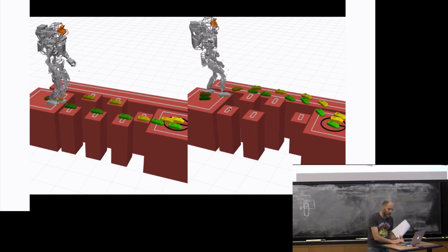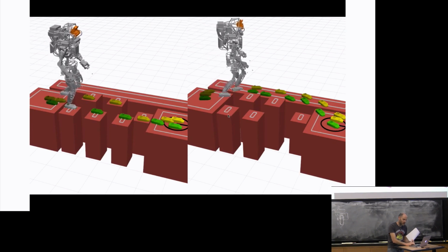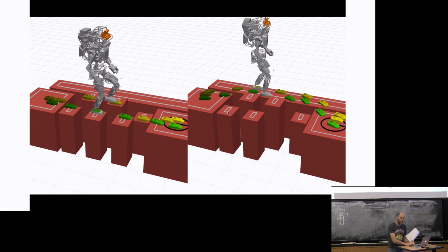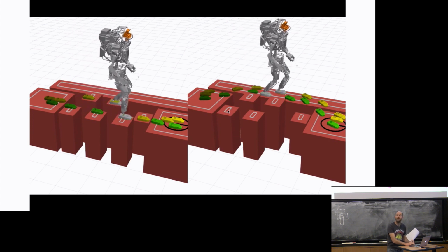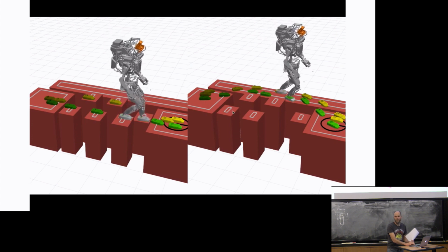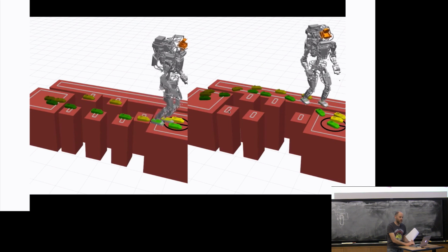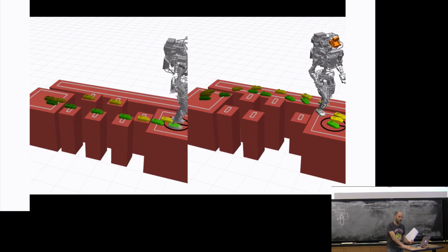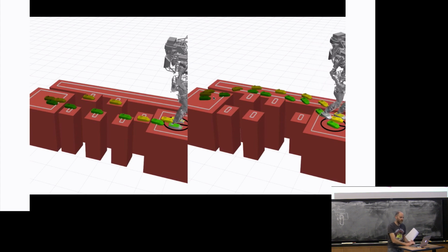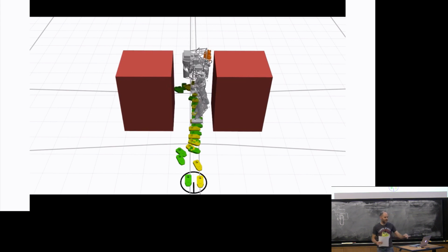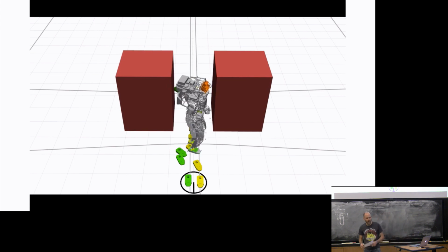The regions now, here you can appreciate they are inside the full step of the full actual region, because the center of the foot has to be inside this set in order for the entire foot to be on the region. So these are the configuration space regions that are admissible for that robot to step in that place. And then a mixed integer convex optimization would assign not only the continuous location of the foot, but also the assignment of foot to region. The reason this is in the video is because that was the case.